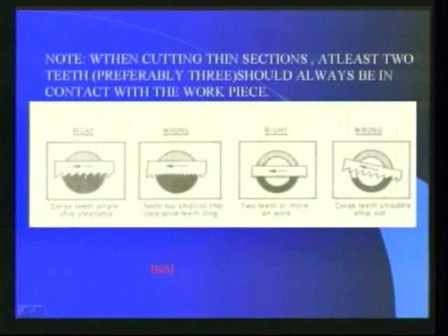Here, for cutting a round rod, coarse teeth blade is used. It gives enough chip clearance. It is the right method. If we use fine pitch blade, small chip clearance, there is a provision to clog the teeth.